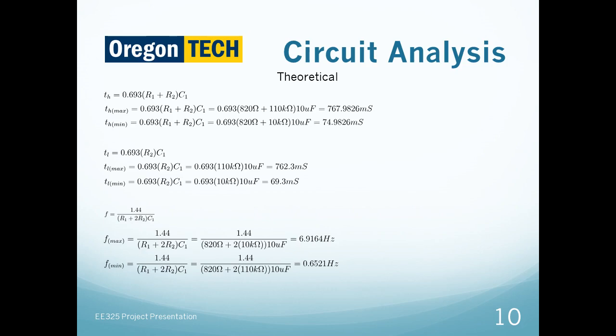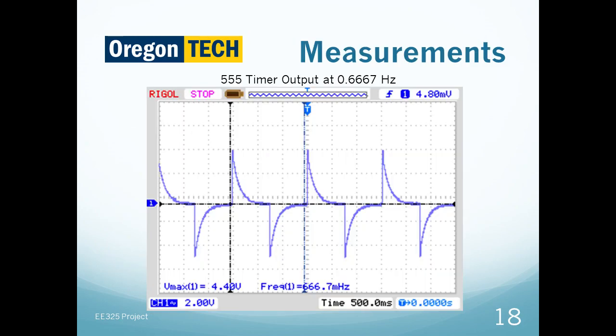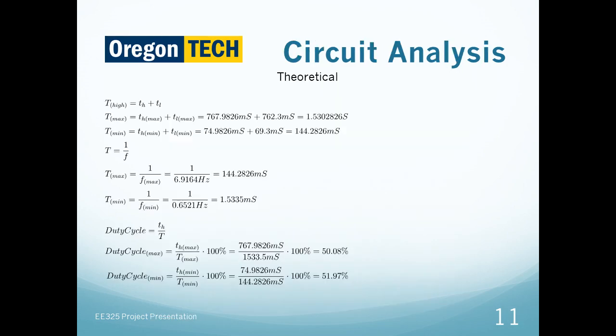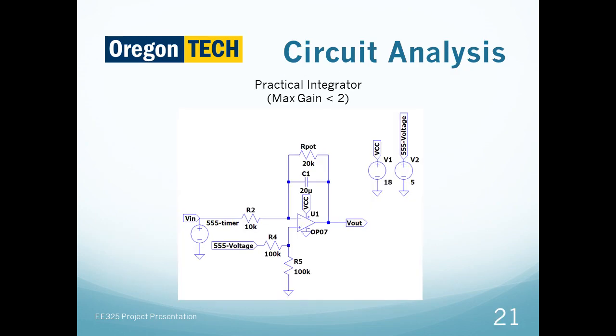A 100 kΩ potentiometer will allow the musician to control the speed of the tremolo effect. In our circuit, the frequency of the 555 has been limited from 0.65 Hz to just under 7 Hz. The duty cycle of this implementation of the 555 timer is fixed to approximately 50%. The intent of Trem-Mellow, as implied in the name, is to provide a subtle tremolo effect.